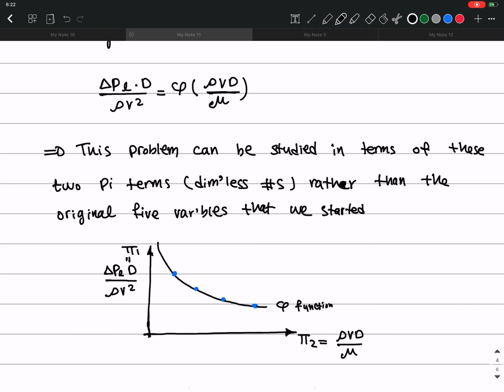So this is very important because especially for nonlinear problems, you're going to use a lot of these dimensionless numbers to be able to find, for example, the losses in pipes, in other things, based on this dimensional analysis, okay? Because these fluid problems are all nonlinear, and we can use this dimensional reduction to find all the relevant relationships based on the experiments, okay?